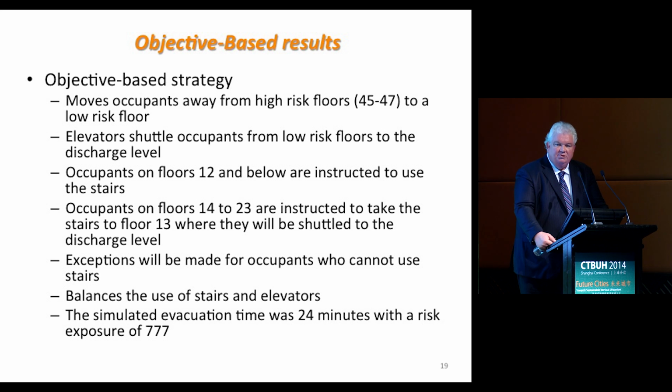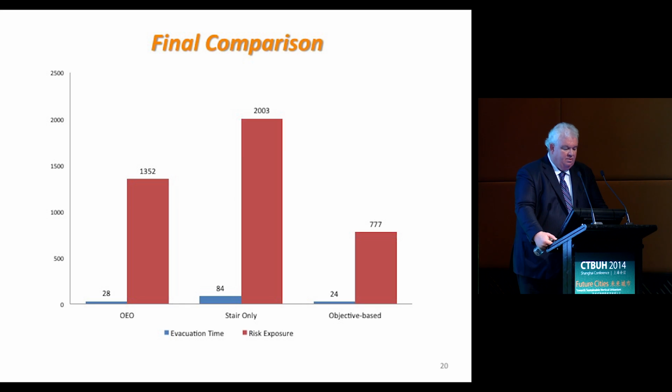So this approach balances the use of stairs and elevators, and the simulated evacuation time was 24 minutes with a risk exposure of 777. So there's a comparison of the 3 approaches. This objective-based approach is obviously a faster evacuation with a lower risk in total to the occupants.